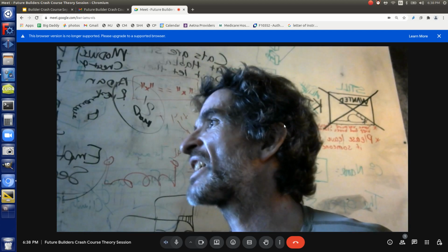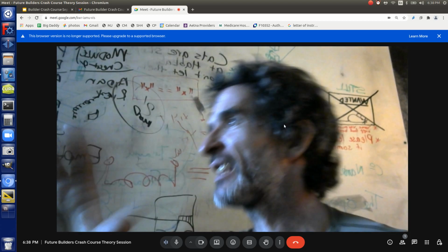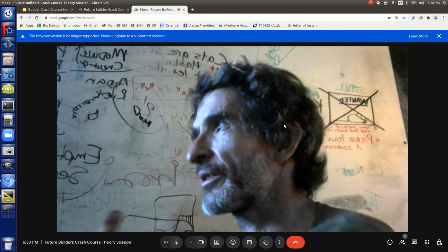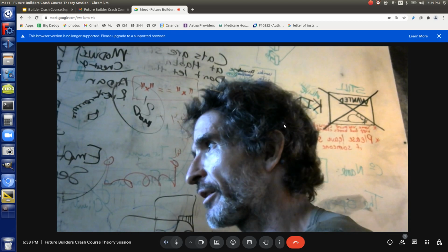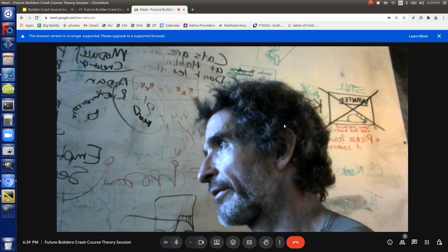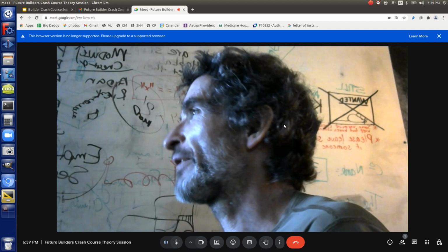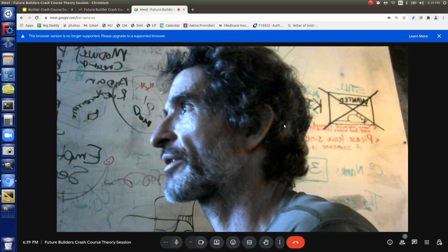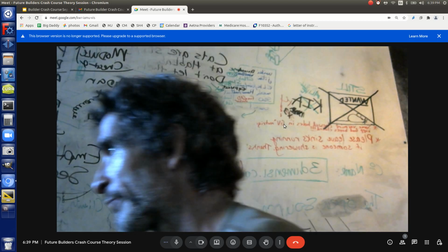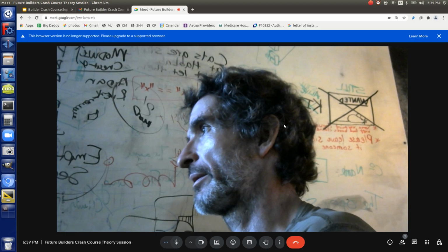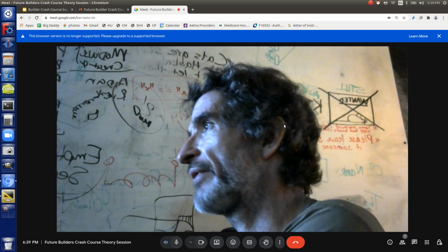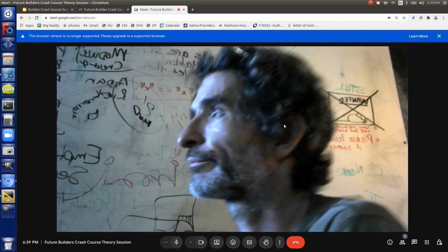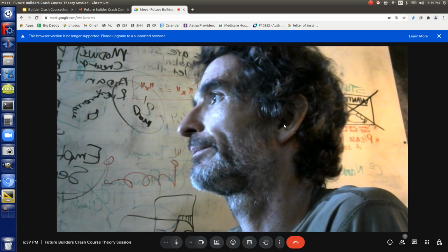Right. Okay, but let's take the ideal brick where the corners haven't gotten chipped and it's actually holding together, which it's not, because on the edge of the brick, the corners are going to start giving away. The brick in the middle of the pile is what you're talking about. Theoretically, that brick is in the middle of other bricks. How much is that one brick responsible for holding? Well, 300 times 72. What's that? It's like 2,000 pounds for that.